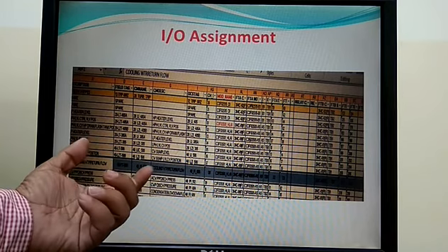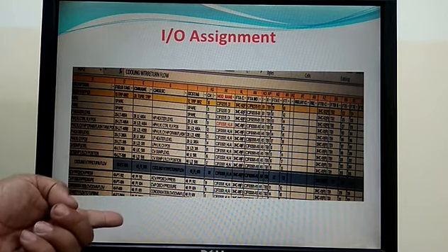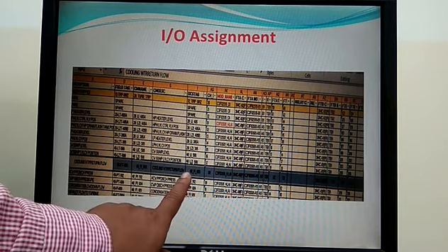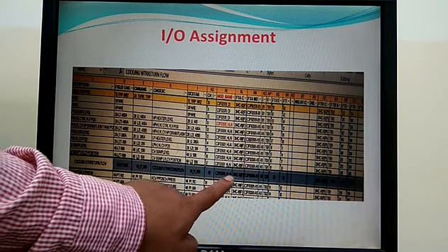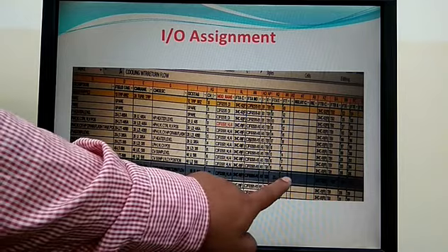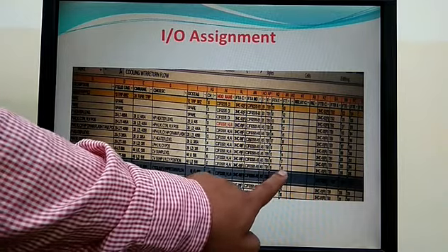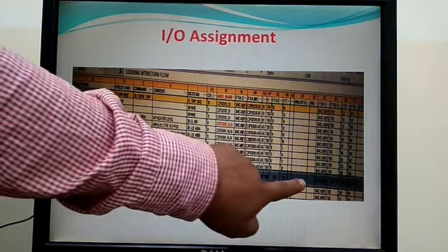You can do it by HART calibrator by configuring the transmitter, and this is your tag. This is your controller channel number, and this is the rear side or back side of the controller. This is where you have to put the AI, the analog signal which is coming out from your transmitter. You have to connect in this location.